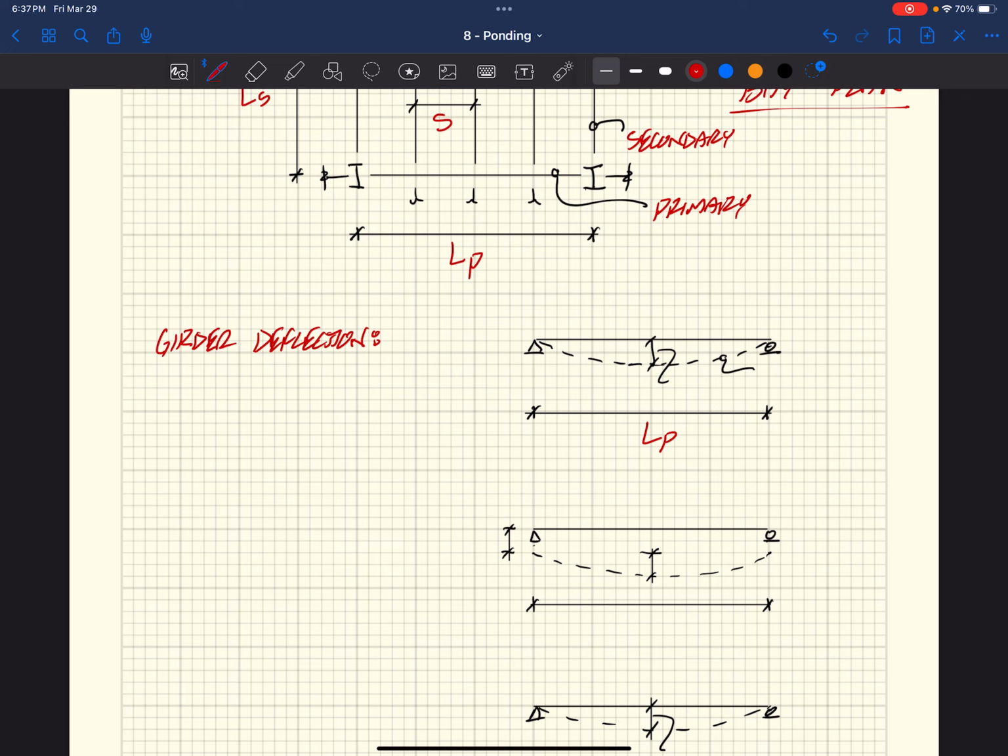And this girder is going to deflect, assuming a uniform load, some amount delta, and that displacement is assumed to be a half sine wave, right? And the reason why it ends up being a half sine wave, or at least why a half sine wave is close enough, is the fact that we made this initial assumption that our loading is uniform,